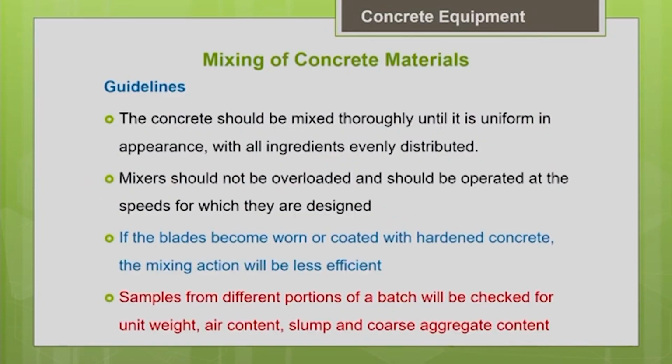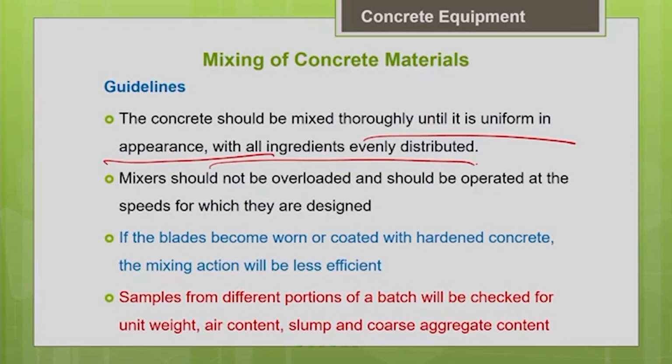Now let us look into some general guidelines with respect to mixing of concrete. You should mix the concrete thoroughly, as I told you, until it is uniform in appearance. Based on experience, by looking at the color itself, you can make a judgment whether the concrete quality is good or not, with all the ingredients evenly distributed. That homogeneous mix is very important. That is why I told you we should go for at least the minimum duration as prescribed by the manufacturer. You should never go below the minimum duration.